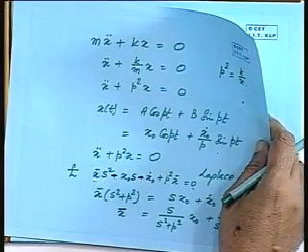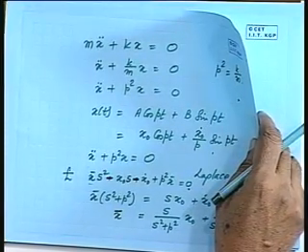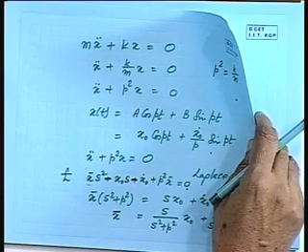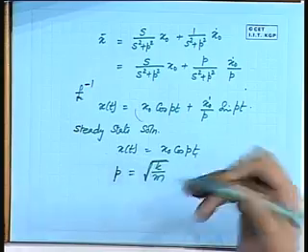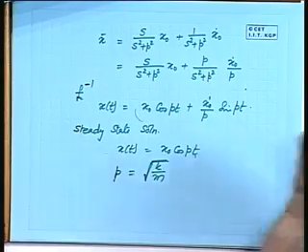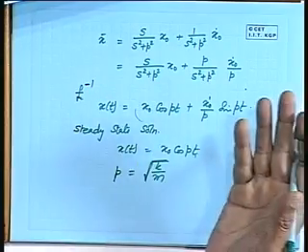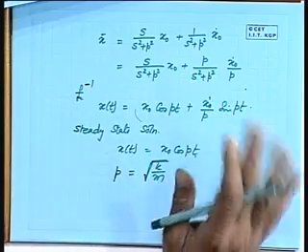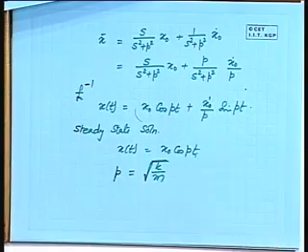Okay. Now, when we take a structure and we find that a particular frequency is not suitable for me. We said that excitation can be all those. Now, those structural items or those machinery etc. for the ship are all bought out items. So, you do not have any control in that, but in the structure which is being designed by you, you have certain control by manipulating K and M. And you know that if you increase the K, the frequency will increase. That means, if you make the structure stiffer, then the frequency will increase.